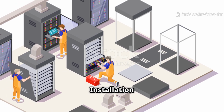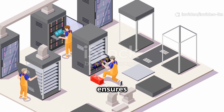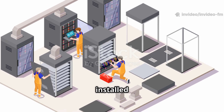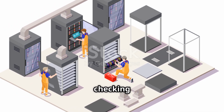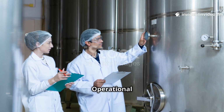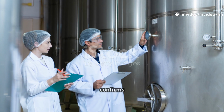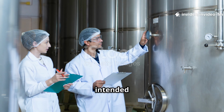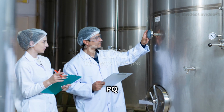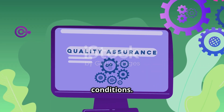4. Installation qualification, IQ, ensures equipment, facilities, utilities, and systems are correctly installed per manufacturer specs, checking proper assembly and utility connections. 5. Operational qualification, OQ, confirms equipment operates as intended under set parameters. 6. Performance qualification, PQ, proves the system consistently performs under real-world conditions.